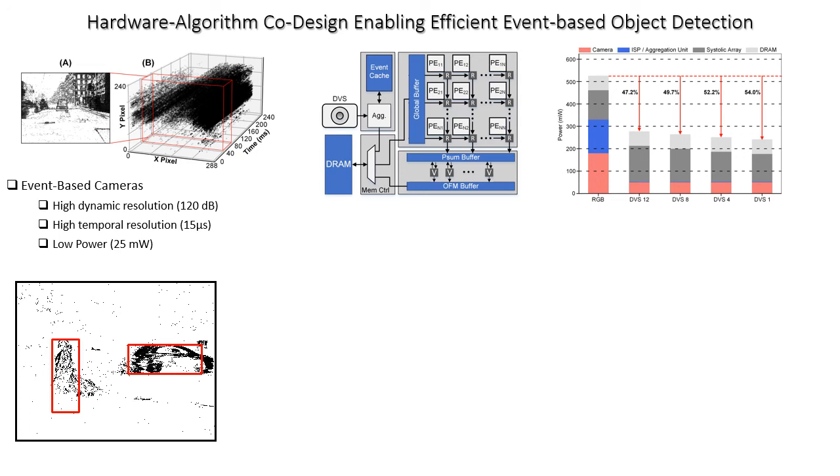We find that because the event-based camera has such low power consumption compared to our reference camera, the AR1335, and because the power consumption of running a small object detection network is low, we can obtain between 1.88 and 2.17x reduction in power while enabling new applications requiring the features of event-based cameras.